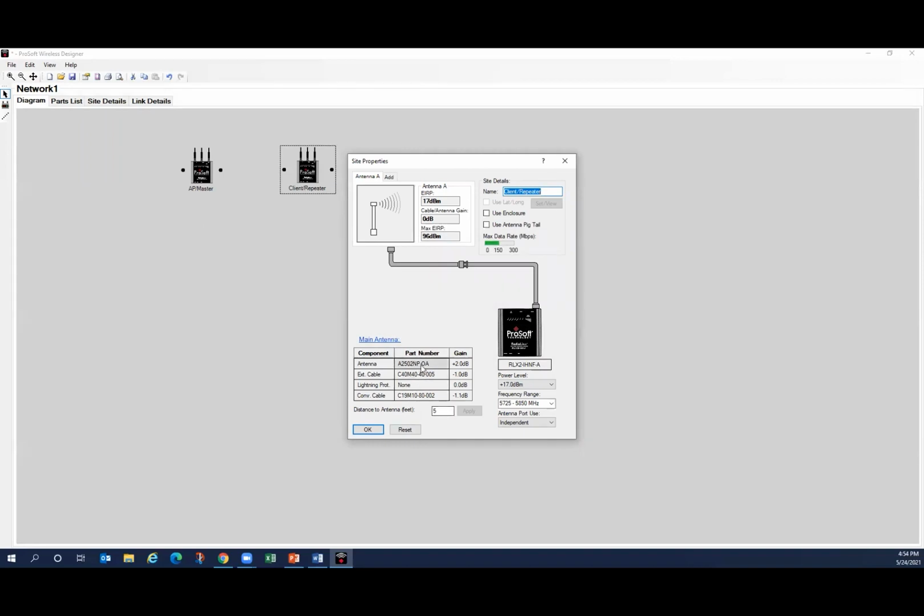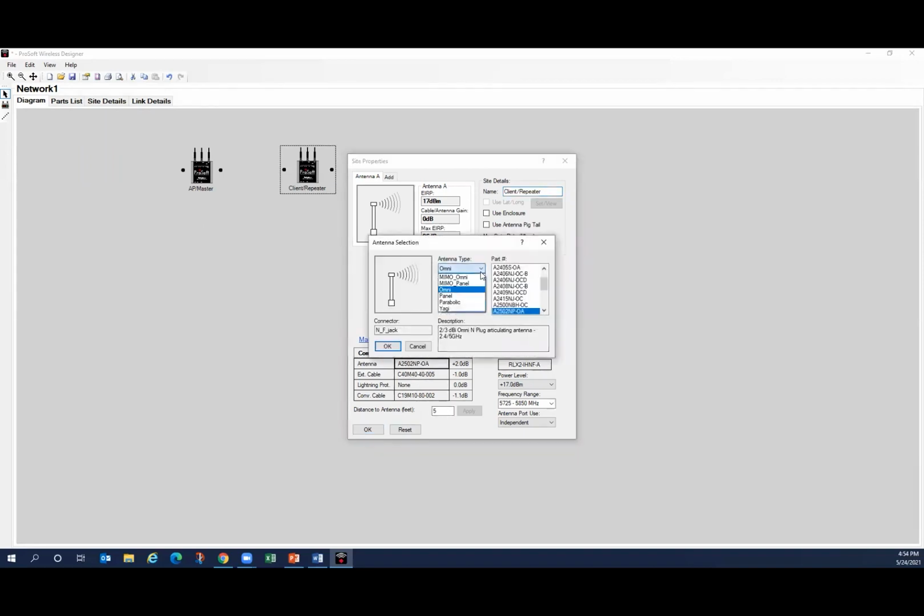Now we can upgrade this antenna again to a MIMO antenna, but let's say this application's fixed. We're looking at the client here. So a directional antenna for the client may be more beneficial. And we can assume that this application has several clients, even though I'm just going to build one in this system. So we'll use this one here, 7 dB hybrid directional.